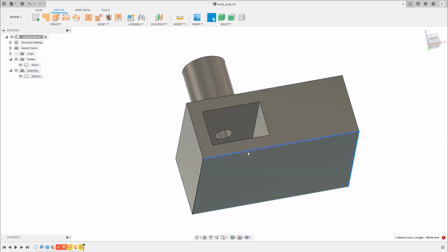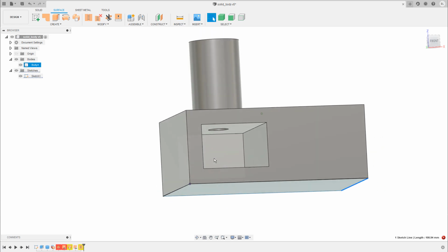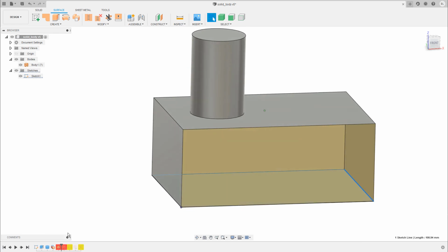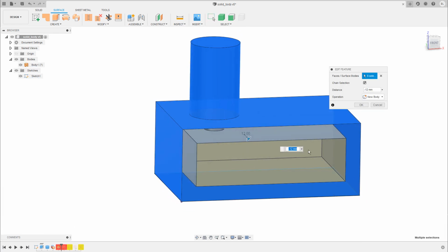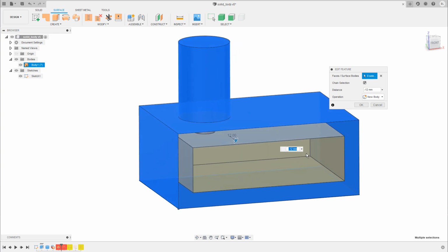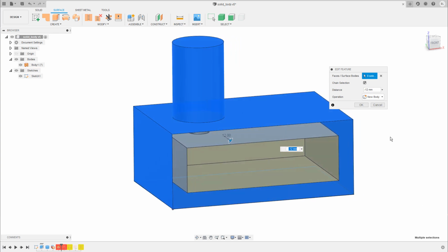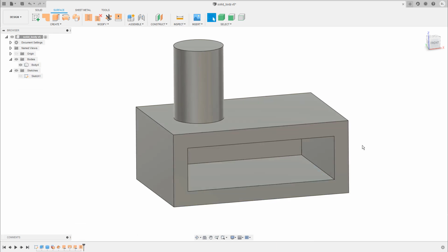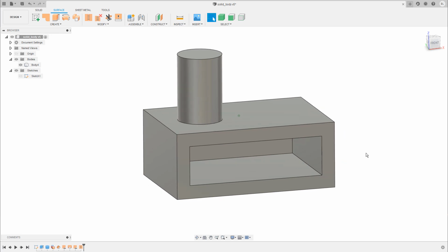It looks kind of right. We still have a solid, but something went wrong with the surface offset here. So I go back to the surface offset, double click on the feature. Here it looks okay. I got no error messages. I click OK on the dialog box and it seems to be fixed. And now I move the slider slowly to the right, watch how the model gets rebuilt, and this small adjustment already seems to fix the problem.